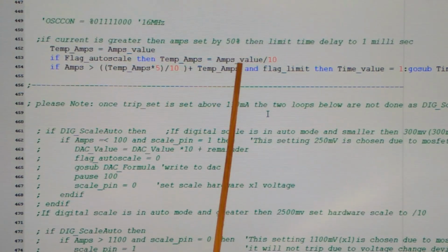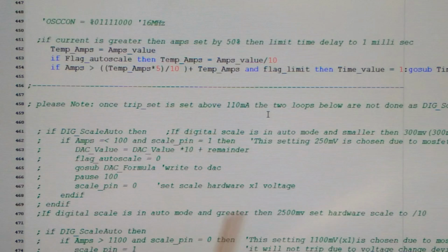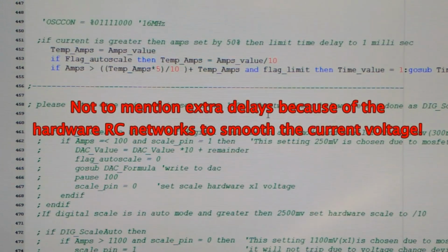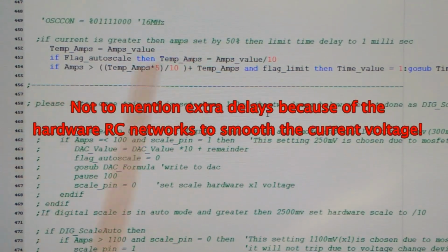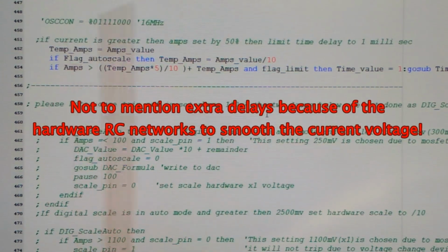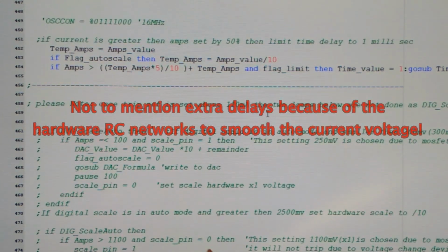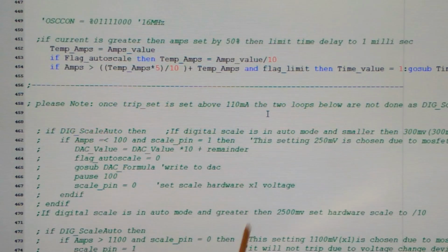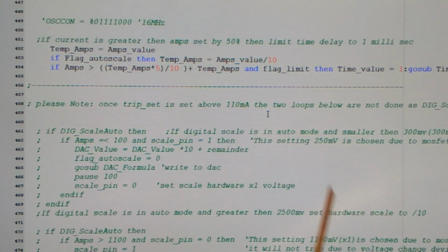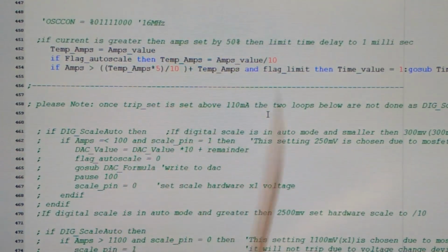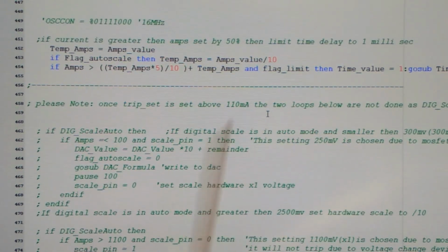I used to, because, you know, just in case there's a short circuit, it's going to wait for 1 second. If you set it to 1 second, you might blow up your SCR or your equipment, whatever you're doing. And again, this is not a very good way because it's relying on the software. If you do it in the hardware actions regarding sensing, it's better than having the software do it for speed. Once the hardware senses it, it's going to be much quicker than your software. There are always delay times in software.